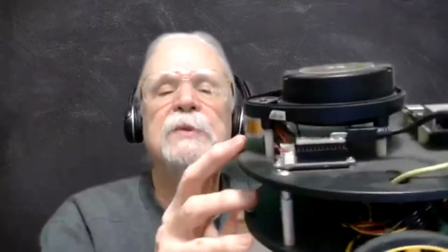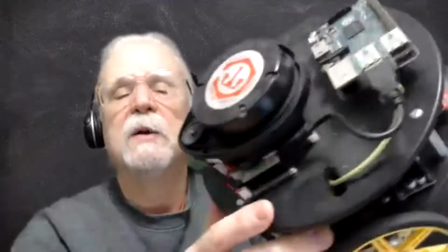Then a guy in the Dallas robotics group built this little translator board that's got a Teensy 2.0 that connects to the laser scanner to control the motor speed. It reads the laser scans, converts them to USB, and the USB goes into the ROS computer, the Raspberry Pi. So essentially, that's the model I showed, what I called my physical model. It's basically the same thing for this little robot as for my medium size one. But my vehicle, which is half the size of a lawn tractor, is basically the same thing you would have for a lawn tractor or a full size tractor.